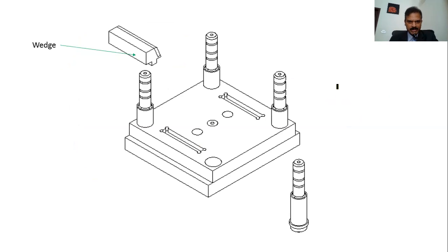Take a look at the fixed half arrangement. This filler is moved away for clarity. You cut two pockets here, and the tenon side of the wedge block has to go and engage in it, to locate. We screw from the bottom. You see the finger cam hole here.